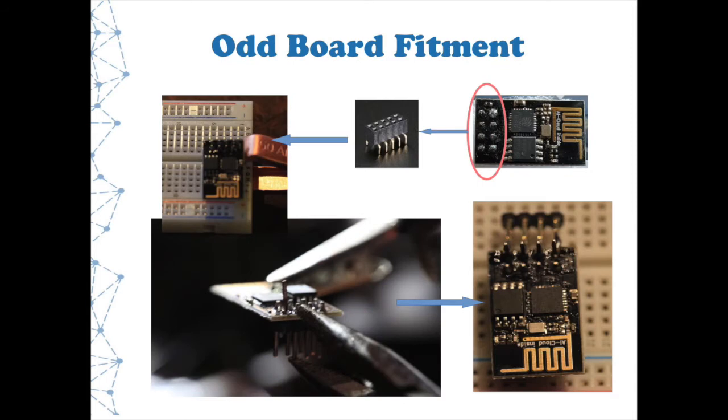Also, this was a weird fitting. The way they had the pinouts on this little thing was a weird fitting pinout, so that it couldn't bridge. Can't point to it, but you have a breadboard like this, and the pins can't bridge the gap in the breadboard because you have pins on one side that deal with power and ground, and on the other might have some I/O kinds of pins. So you have to have a way for that to work on a breadboard. So I got this little adapter, but then the output pins on it were too small to fit into the breadboard. They weren't the same kind of pin layout. So I just clamped it with a battery clamp to the board so that it stuck and made contact electrically, which sucks, right? Because this is all hokey now.